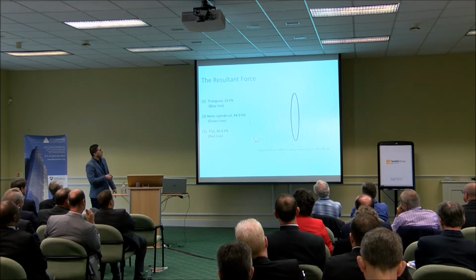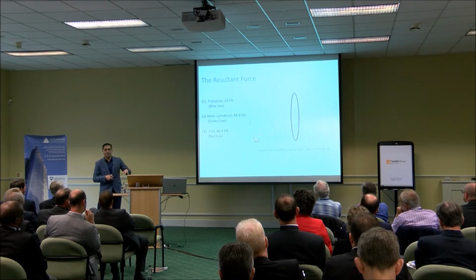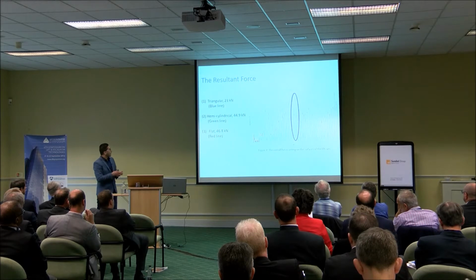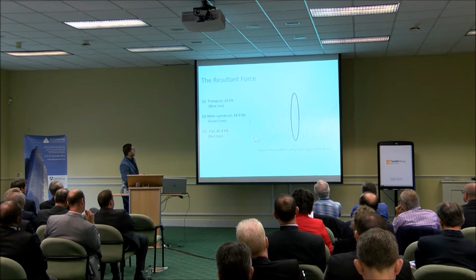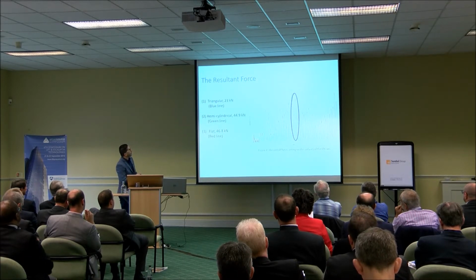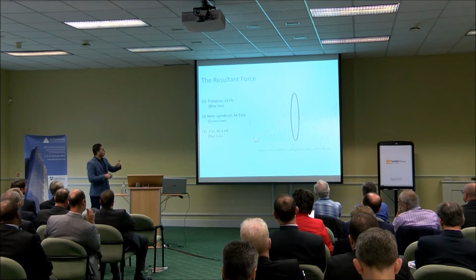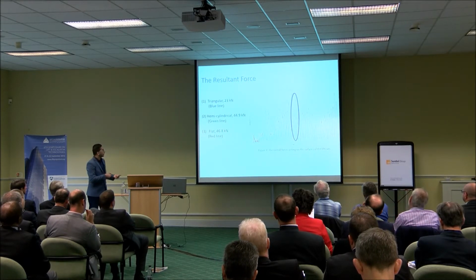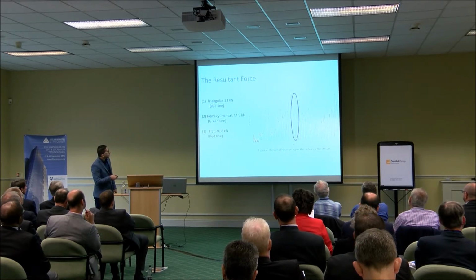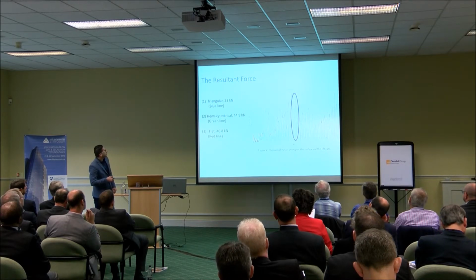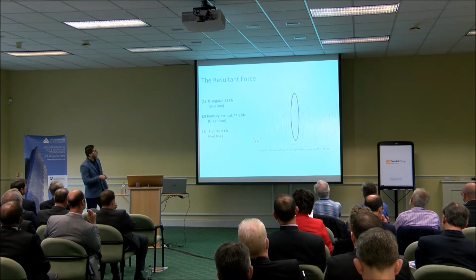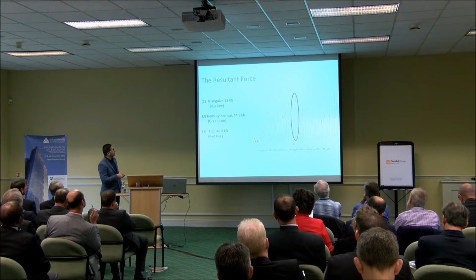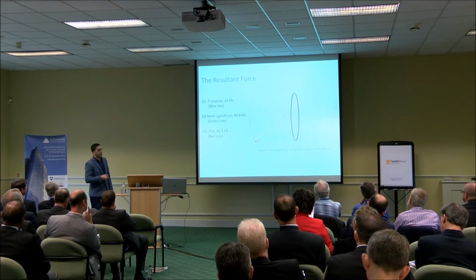These fluctuations show the overall forces that are acting on the lift surfaces. Now the color coding has been changed. The red line represents the resultant force that acts on the flat lift, which is the highest value, 46.8 kilonewton, and the green line represents the resultant force that acts on the hemi-cylindrical lift, and we have the lowest value, 23 kilonewton, which acts on the triangular lift.